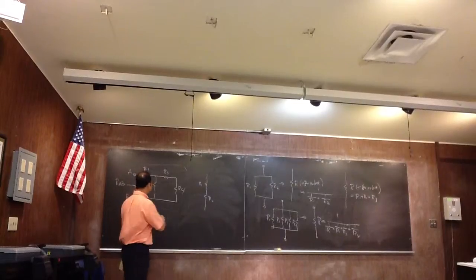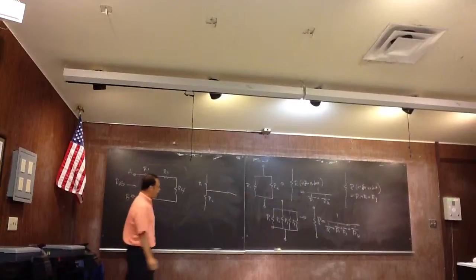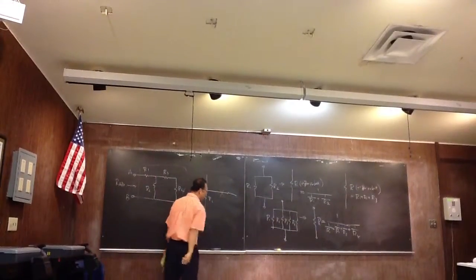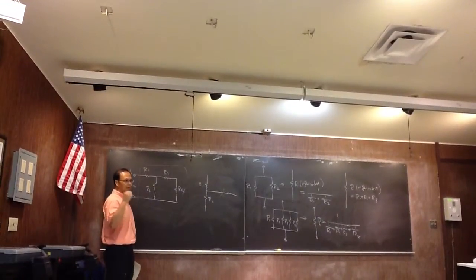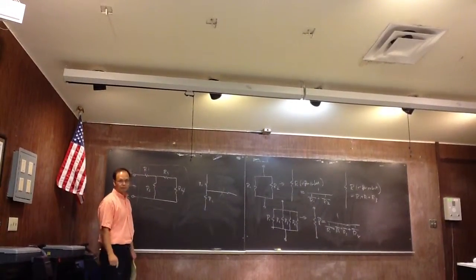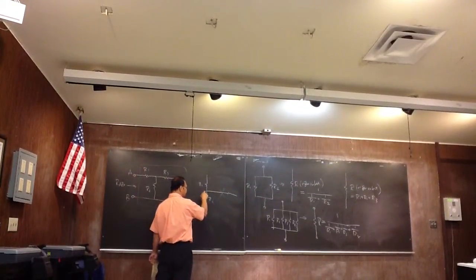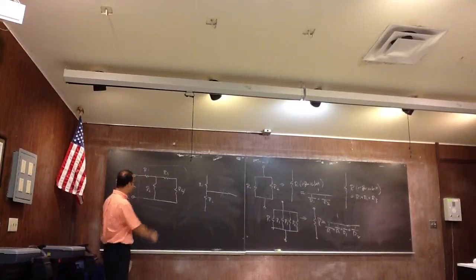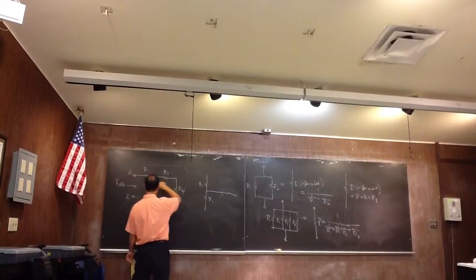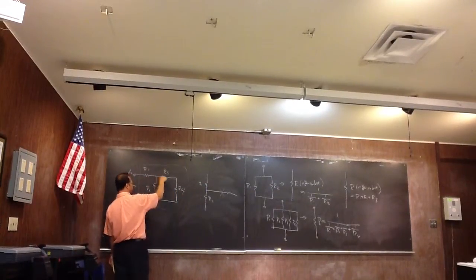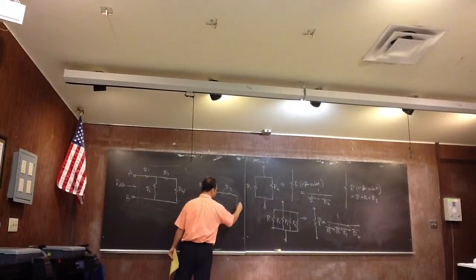Unfortunately, it's not, because we have something that is sticking between R1 and R2, and that does not allow you to use the concept of the series connection. When you say series, that means I have this in connection, but I have nothing else in the middle. But I do have something in the middle. You have R3 and R4.